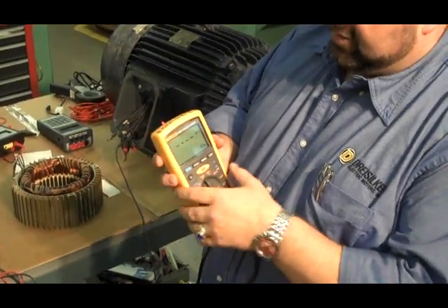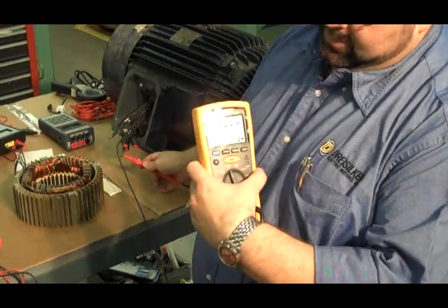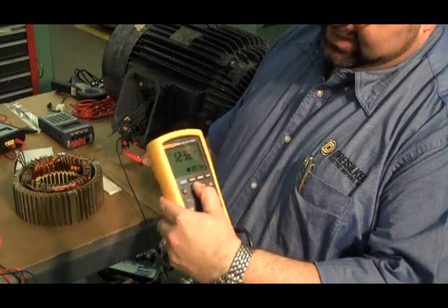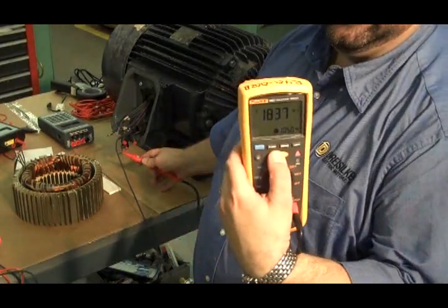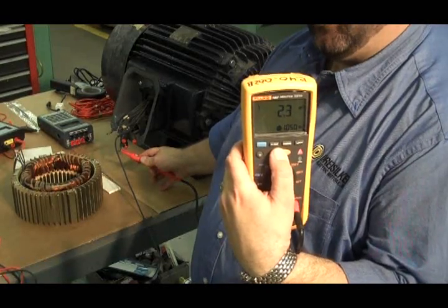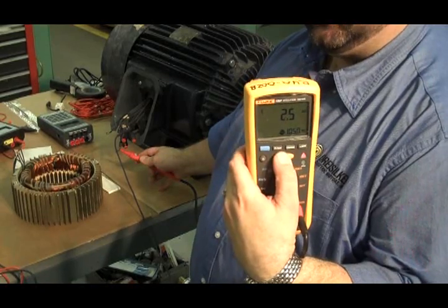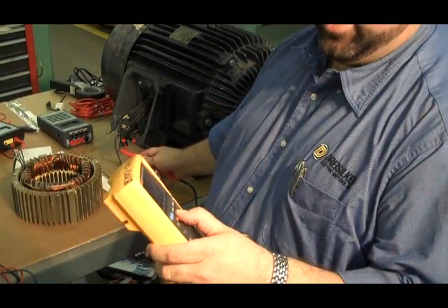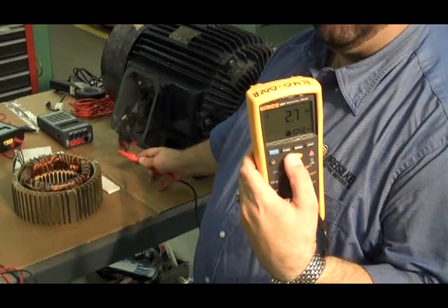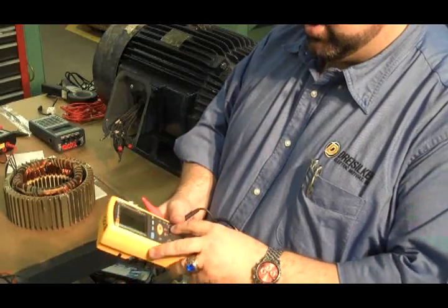But if I go to 1,000 volts, once I start up, I will get into an area called the gigohms, and if I go into hundreds of thousands of megohms or thousands of gigohms, that's called a teraohm. So as I hold this, I look here and I'm at 2.6 gigohms.